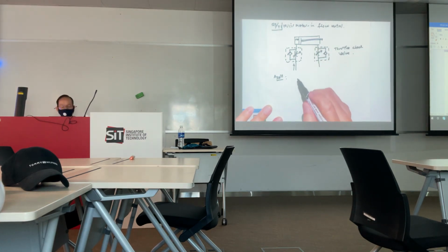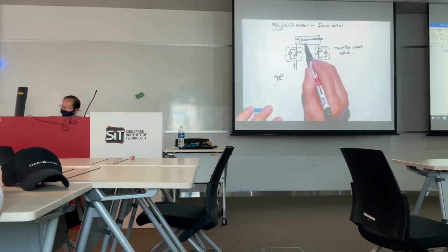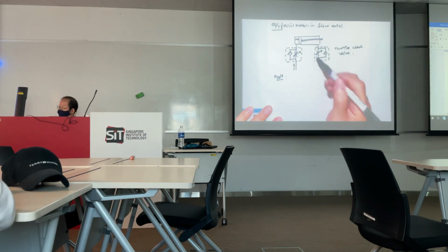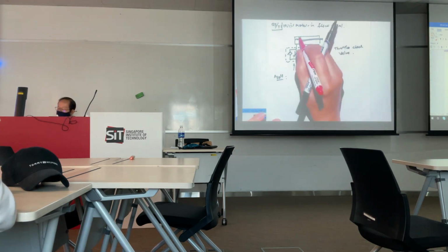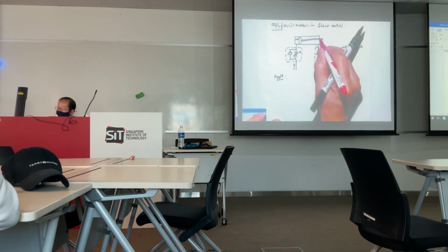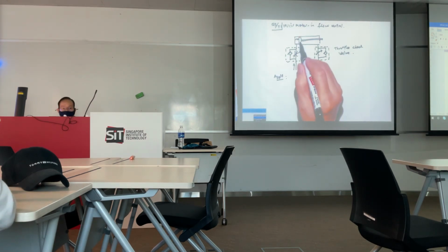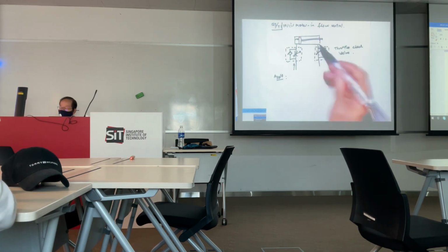So what's the application in this case? Forward there's a force. On this side, there's no resisting force other than some back pressure and the seal frictional resistance. We can assume the back pressure and the seal frictional resistance are negligible. It is a very reasonable assumption because it's very low compared to the forward force.